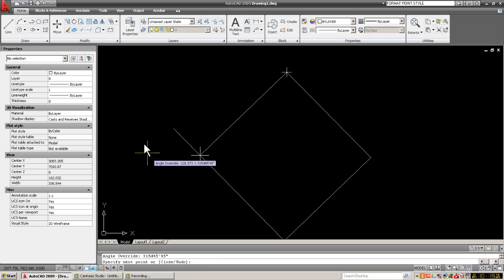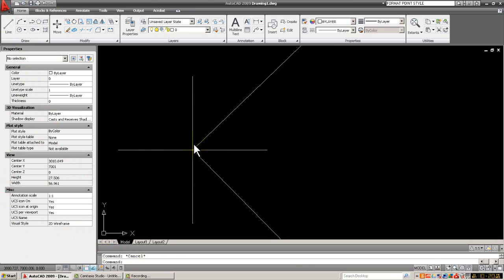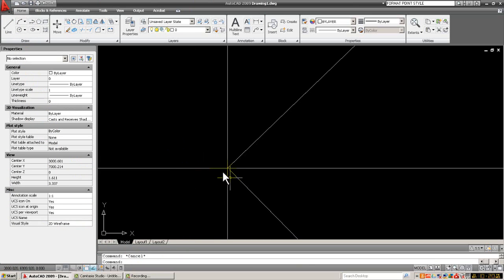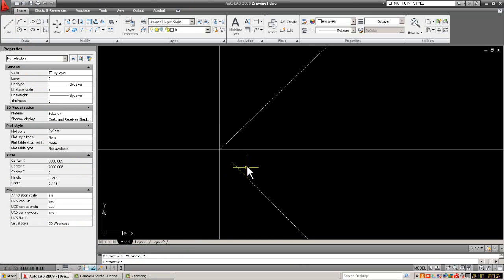And there's our angle override, and that should be 100, but let's say for measurement's sake it became 99.98 rather than 100, which should give us a little bit of a misclose in there. So we'll just go in there and have a look. You would expect that it doesn't quite come back to the start there, and that of course would be our misclose.